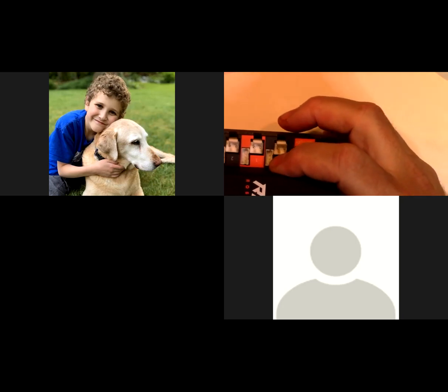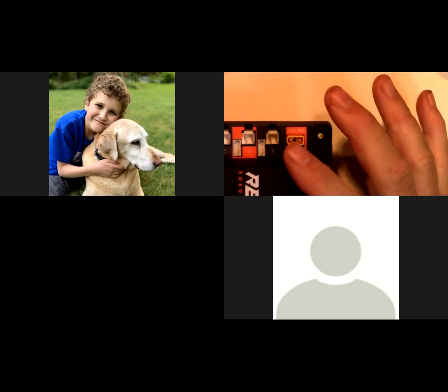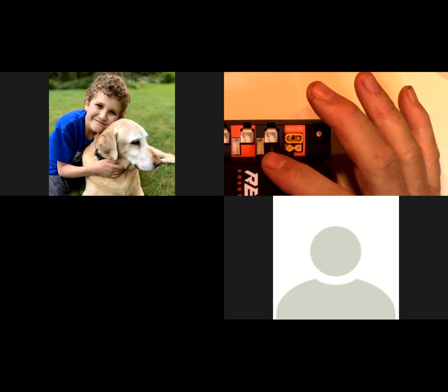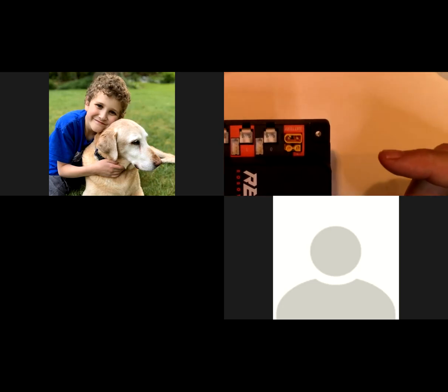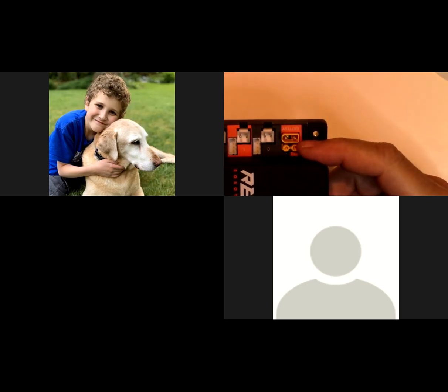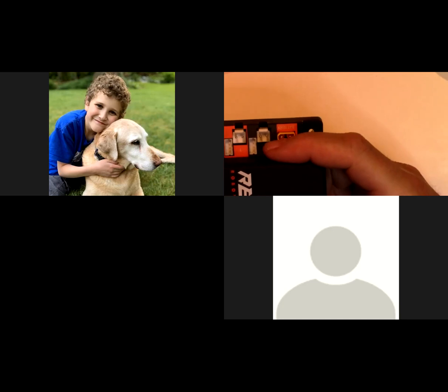The other thing right next to it is a connection for the shaft encoders. I was telling you the backs of these motors all have shaft encoders that will allow you to know, like I said, about 1,020 clicks per revolution. You get more feedback about how the motor is doing. Yep, it's feedback, and it allows you to do PID. I don't know if you're familiar with that. The motor class in software actually has PID built right in, so you're able to rely on PID algorithms a lot. And we all use them quite a bit.